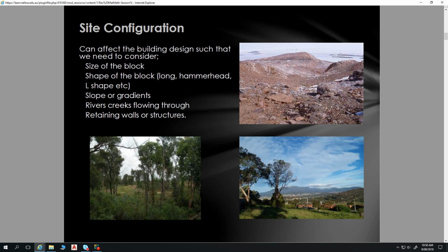They require a road of a certain length, a certain turnaround, and that has to be maximum slope of 1 metre rise and 3.5 metres of run. Is the slope of the block going to stop that happening? You have to also think about entry point for a CFS truck. It also has to be 4.5 wide and 8 metres high. 8 metres high, is it? If you're in a country area with overhanging trees. Yeah. And an external radius of corners of 12.5 metres.